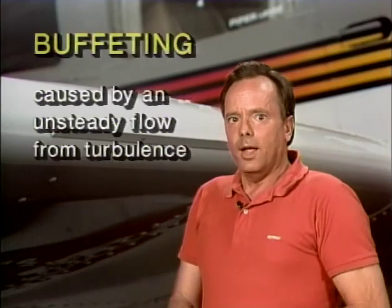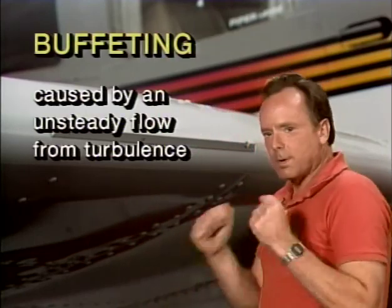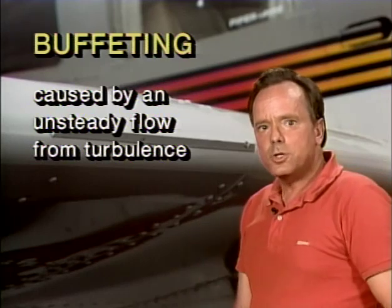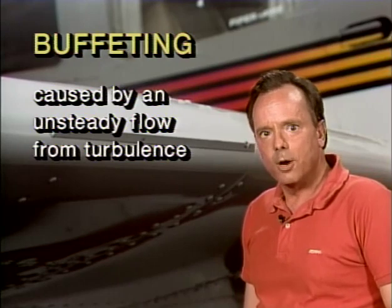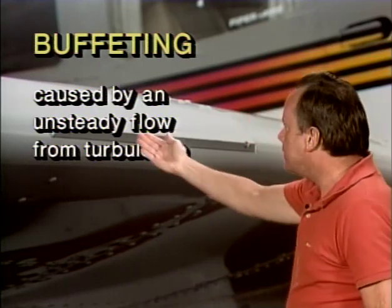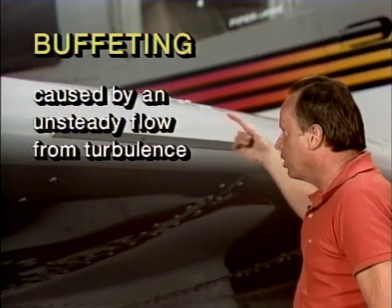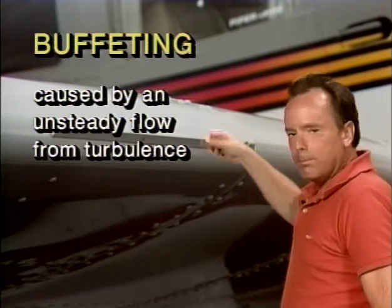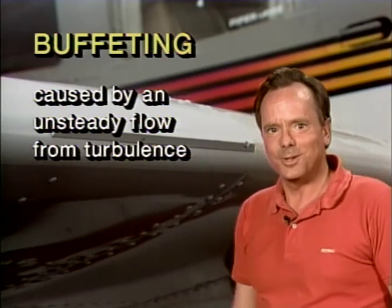Now they ask you some questions on buffeting, and buffeting occurs, by the way, sometimes when you're in a stall, and what it is is a banging on the aircraft. And they want you to know it's what's called the intermittent application of forces to a part of the airplane caused by unsteady flow from turbulence. So when you're stalling an airplane, you're actually creating turbulence, and then you have buffeting on the aircraft, and it's the intermittent application of forces on the aircraft.